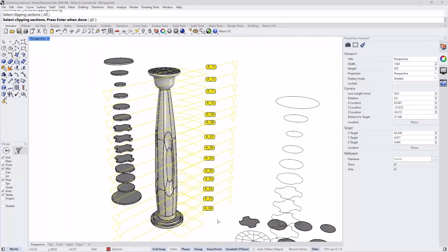Well, that's actually the question I'm asking you. If you take a slice of your solid object, you get an upper outline and a lower outline, and then you need to project those onto a common plane and capture the perimeter of those two outlines, the maximal perimeter, and that becomes the outline that you drive your laser.